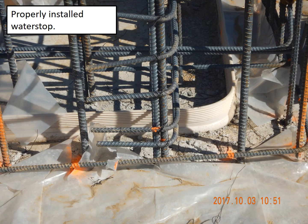Here's a good example of a properly installed water stop. You can see it's halfway embedded in, so that center bulb is partially sticking out of this existing concrete. We've got this rebar cage here that's nicely tied. This is the base of a riser here, and we're going to be pouring the concrete walls shortly after. But that PVC water stop is mostly free from any kind of laitance material or overpour of concrete.